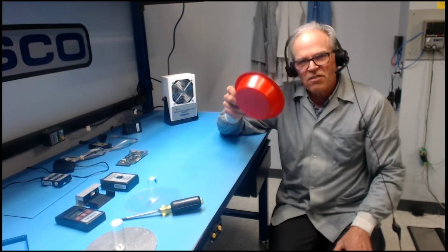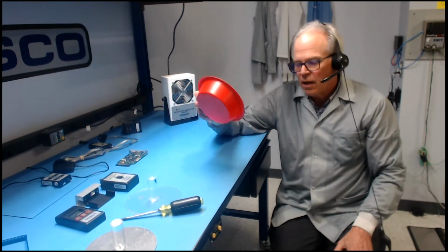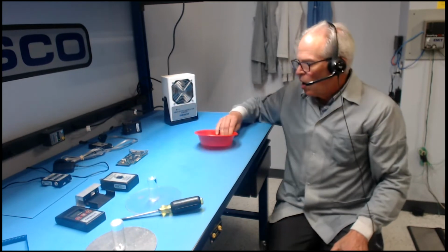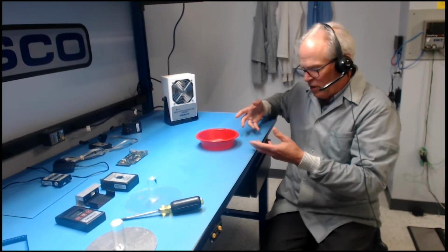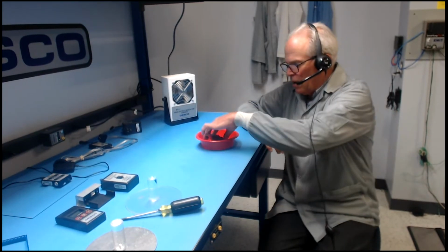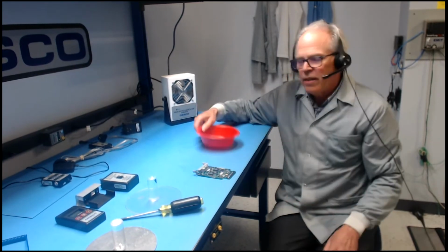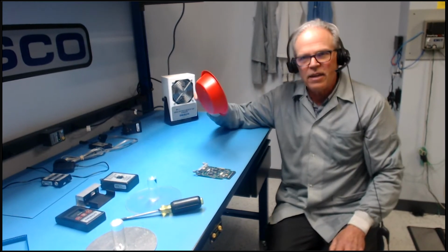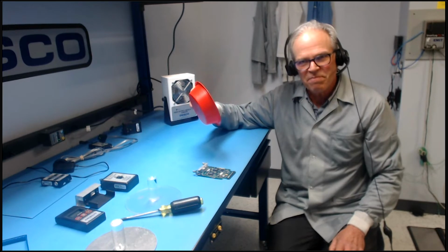So let's say it's a fast moving conveyor belt, and every 8 seconds, a headlight comes in front of a person, they take the board, and they put it in. That ionizer has to take the charge off of that headlight in 8 seconds or less.